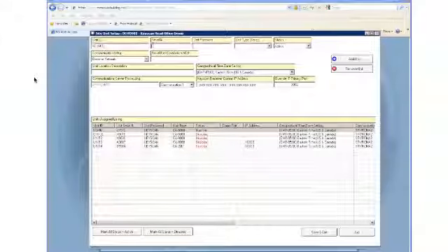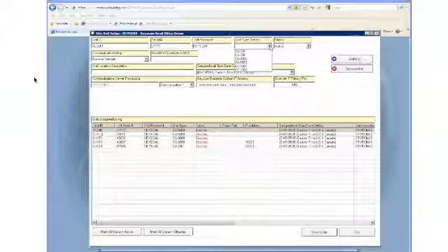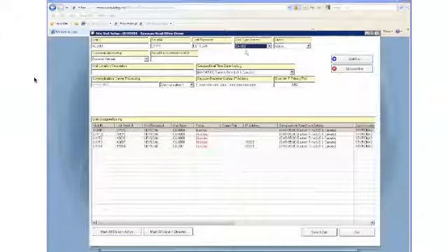Next, enter your serial number of the CA150. Enter the default password, which will be Keyscan, all capital letters. Select the unit type. In this case, we are using a CA100 series. Leave the status as active. This will allow the panel to connect automatically once we connect it in the field.